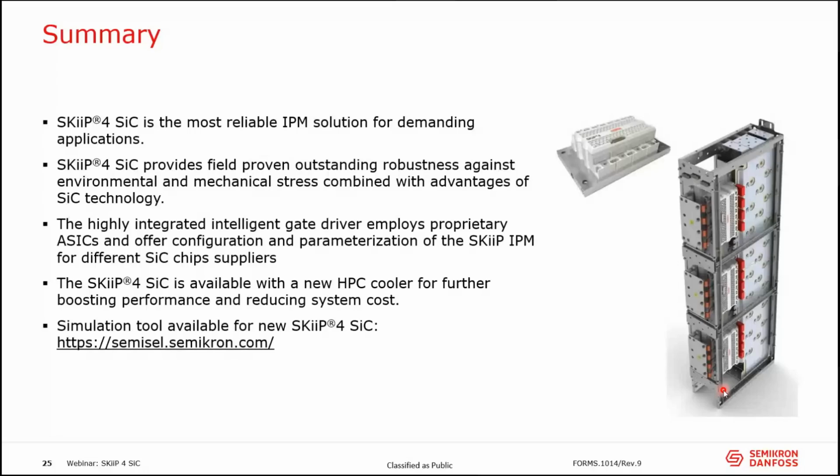We have the short driver test, and we make a burn-in test that is like temperature cycling in our production. The SKiiPs are tested for almost 1 hour at the operating junction temperature, close to the maximal operation temperature, so that early failures and defects in the chips can be sorted out in our production and do not come to our customers.